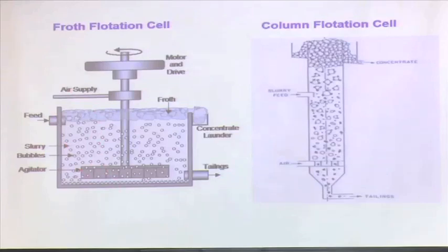Okay. Now, think of the scenario. Normally, it has been observed that the particles which are hydrophobic are aerophilic. If they do not like water, in most cases they like air. So, they will be attached to the surfaces of my air bubbles; selectively the hydrophobic particles will be lifted up, and there will be some foaming, we call it froth.